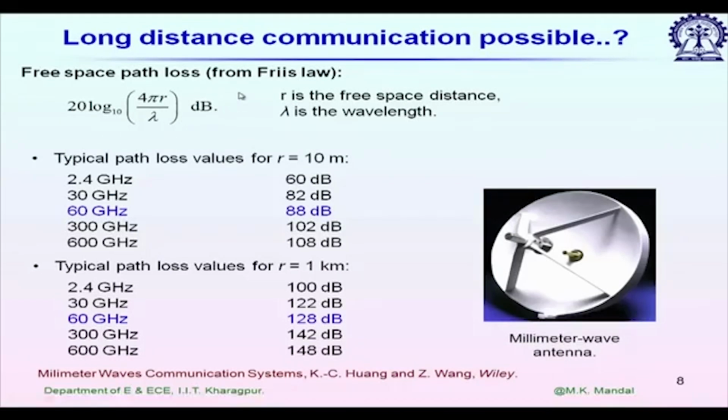You can consider one transmitter, let us say it is placed at the origin of a polar coordinate system, and it is transmitting in all directions. Now, I have a receiving antenna. So, the received power by my receiving antenna depends on the effective aperture of this receiving antenna. So, we can consider a spherical surface, and the receiving antenna is placed on that surface.